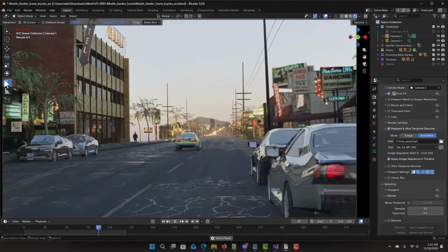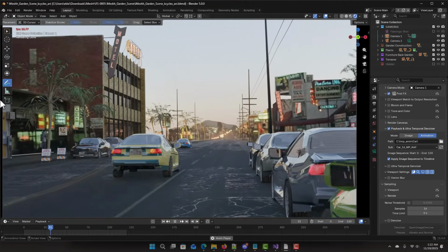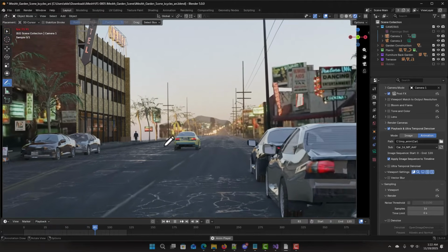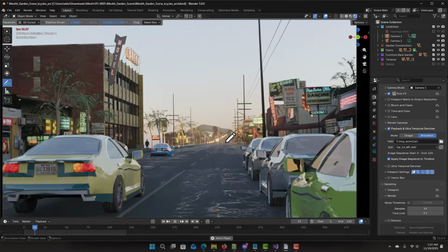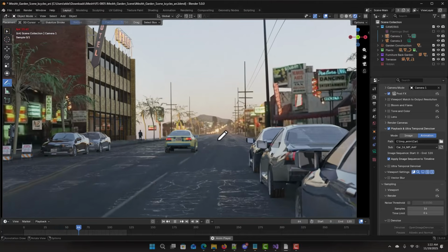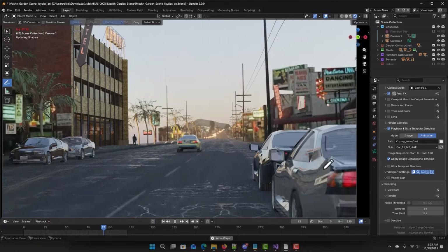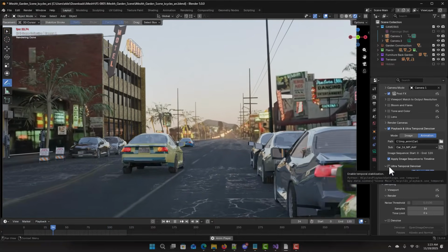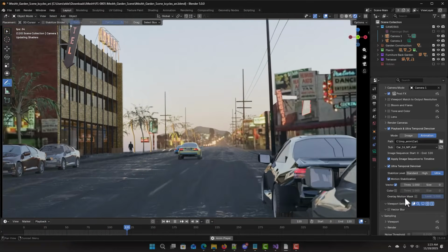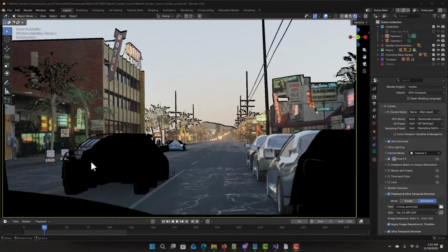Here's a car scene that has both camera movement and object car motion. Here, the flicker is not too high, but you can mainly notice it in the reflections on the streets. It's got a bit of flickering on the reflections on the street and on some of the buildings' walls. We're going to turn on now the Ultra Temporal Denoiser, Stable Modulation, and the mask. The motion vector mask follows the object motion, in this case the car, and we're going to see how much ghosting happens in this image to adjust the proper threshold to get a clean image with good flicker reduction.